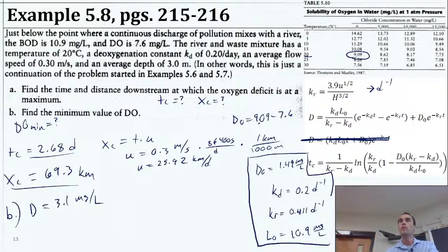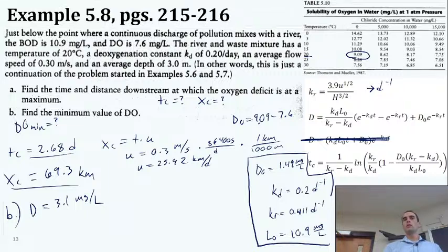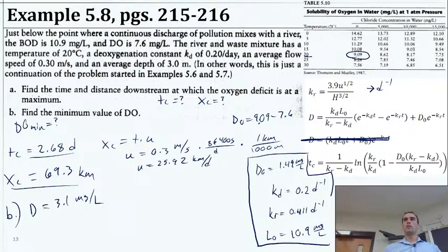Did I get something wrong? Back on one of the beginning ones, why don't you just set the accumulation equal to 0? The equation has a couple of fewer terms, and you get the same thing. Why don't I set what to 0? So for modeling the deficit, the accumulation equals the deoxygenation rate minus the reaeration rate. If you just set the accumulation at 0 and solve for D, you have an equation that's less cumbersome, and you get the exact same thing.